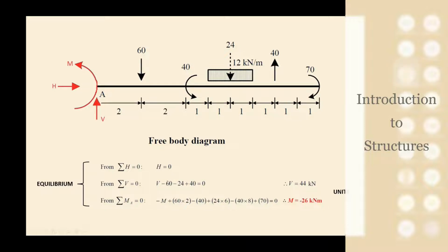Well, we have used the summation of forces in the horizontal direction and in the vertical direction. So now it's time to apply the summation of moments to calculate the moment as a reaction, in red on the screen. In cantilever beams, we choose to do summation of moments at the point where the fixed support is applied. So we are going to do summation of moments around the point A, and this summation of moments needs to be equal to 0. This is again mandatory because this is the principle we are using.